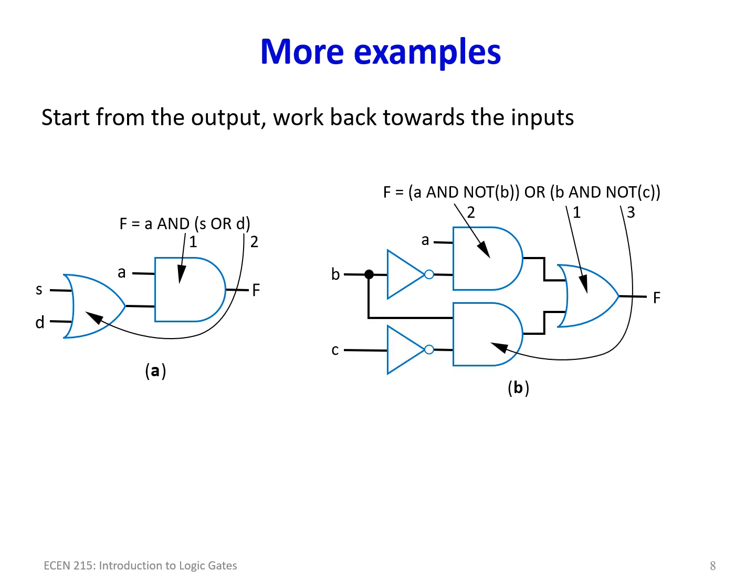And look at what we did here. Since we had B in both cases, we just created a node, an electrical node, and we just brought B directly in here. There's no harm. You can also just write B here and not have any of this wire, just have a separate wire. But it's convenient sometimes to go ahead and show this because electrically that is what's happening. B is being shared and coming here. This here is obviously B prime. Of course, this is A, and this is A, B prime here.